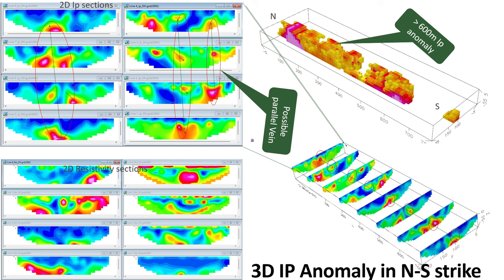We use that target to say, okay, we are close to what we are looking for. Seeing that, we're able to conduct some resistivity in those locations, and they show a very interesting anomaly striking in the north-south direction, and they're very continuous. You can see them here, and also here where we try to model it in a block form. We try to see where the high resistivity is actually concentrating. We found out that they're actually in the north-south direction.